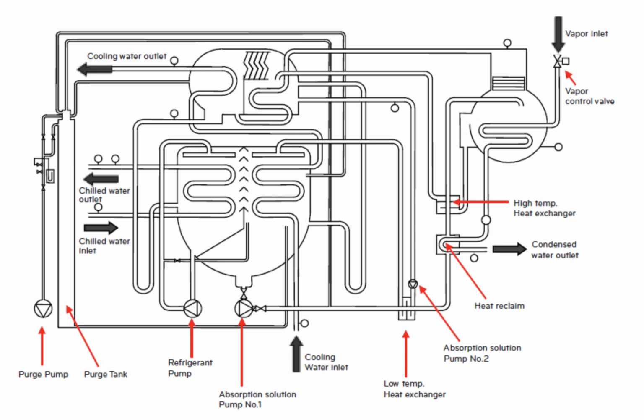Flow of absorption solution in cooling. Absorption solution drops from the tray on the upper part of the absorber onto the heat transfer tubes inside the absorber and gathers at the bottom, absorbing refrigerant that comes from an eliminator. At this time, the absorption solution becomes much more diluted than before it flowed onto the tray.